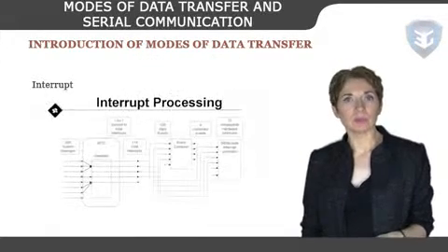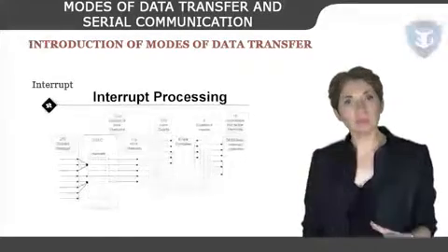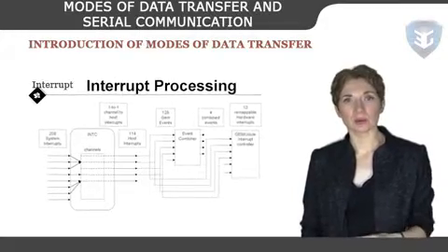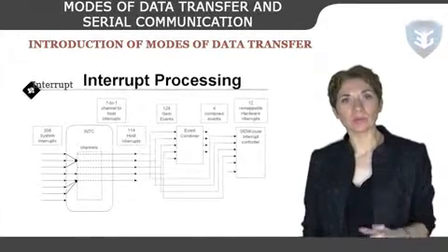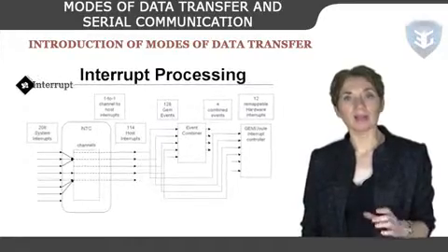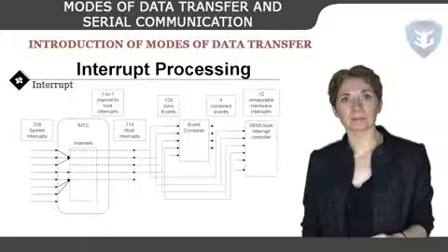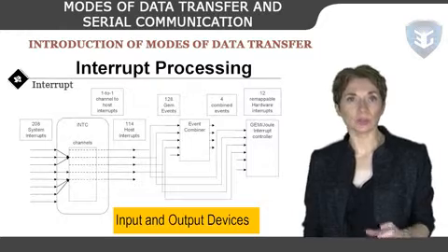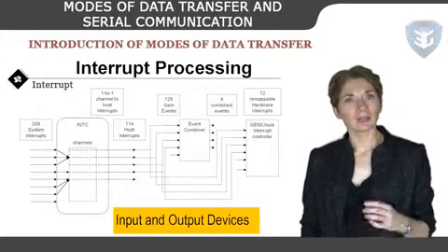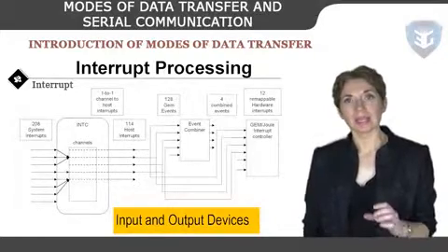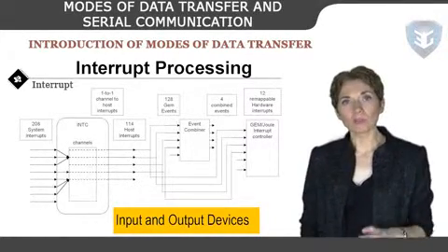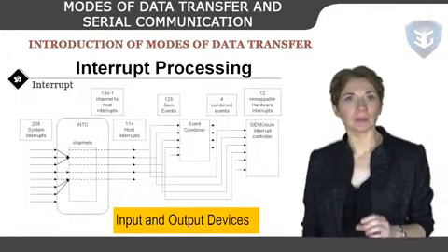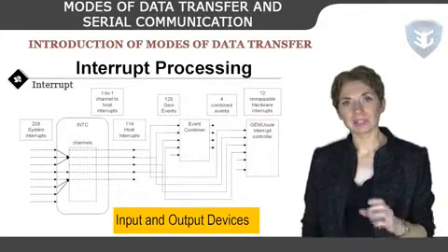Interrupt. The CPU issues commands to the I/O module, then proceeds with its normal work until interrupted by an I/O device on completion of its work. For input, the device interrupts the CPU when new data has arrived and is ready to be retrieved by the system processor. The actual actions to perform depend on whether the device uses I/O ports or memory mapping. For output, the device delivers an interrupt, either when it is ready to accept new data or to acknowledge a successful data transfer. Memory mapped and DMA capable devices usually generate interrupts to tell the system they are done with the buffer.